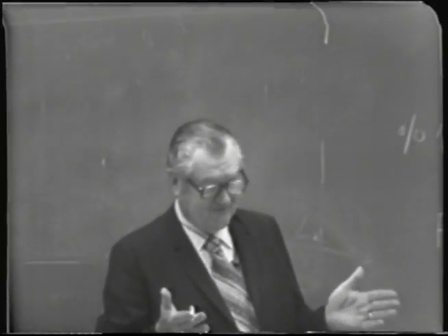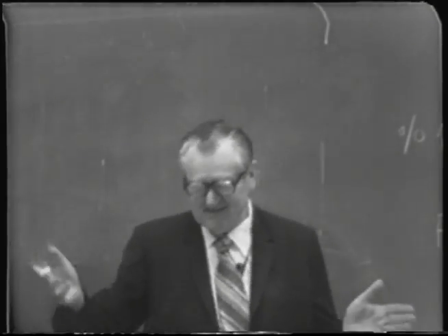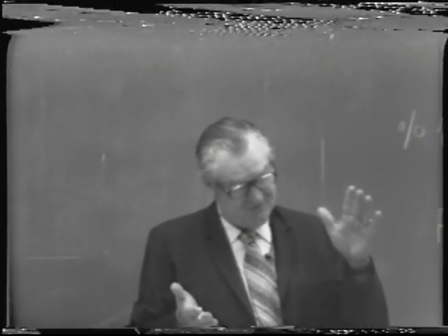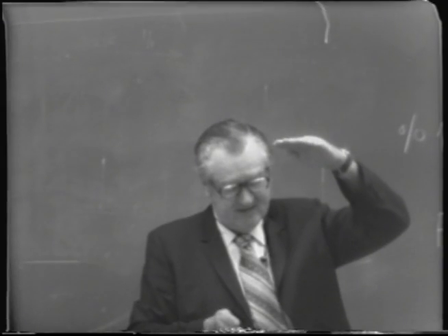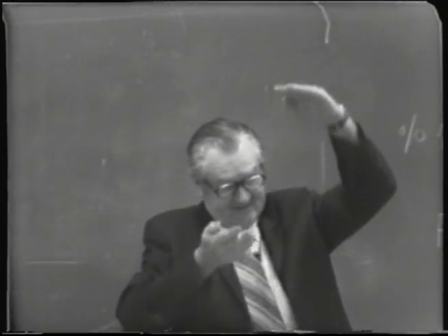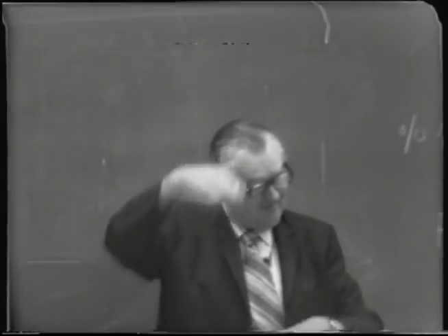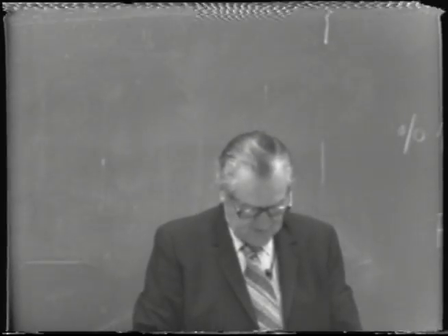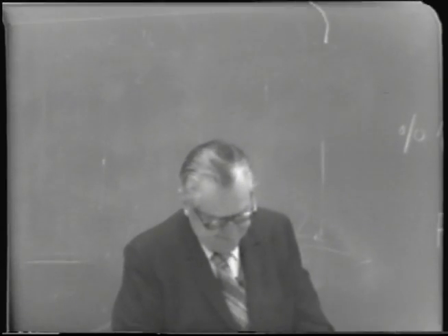You still have to figure out the number of ideal trays, and then if you have some knowledge of what the height of a packing is equal to one theoretical tray, then you have that much height, or have to have that much size.